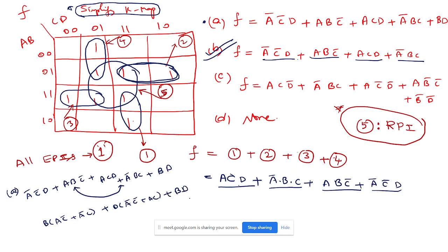See, if you say, I have solved a Boolean expression using the Karnaugh map and you stated your final answer, then nobody should be able to simplify that. If somebody has done simplification of whatever the answer you said, then you have not done it in Karnaugh map rules. That's the point I'm trying to say.